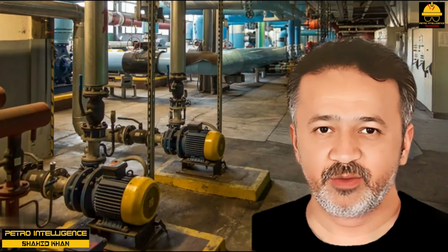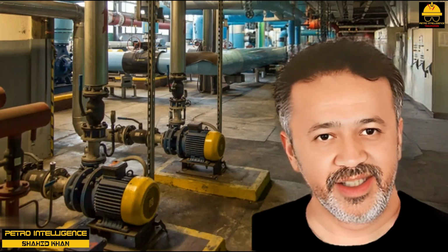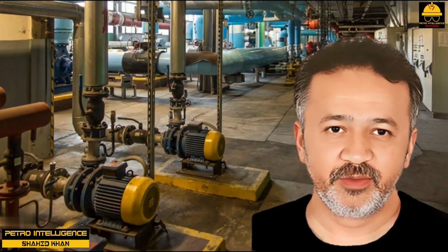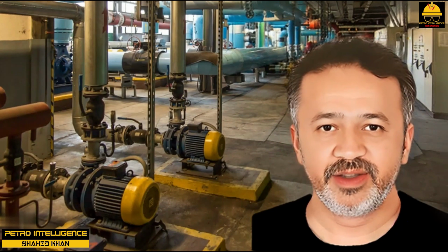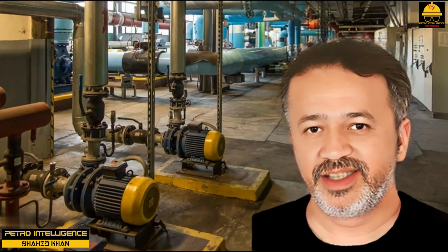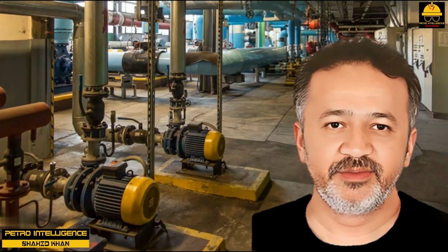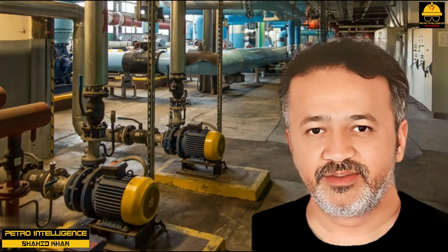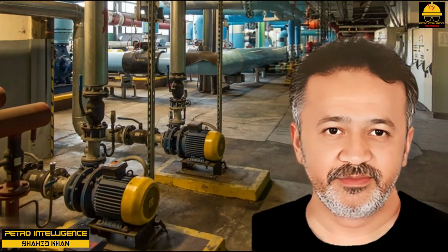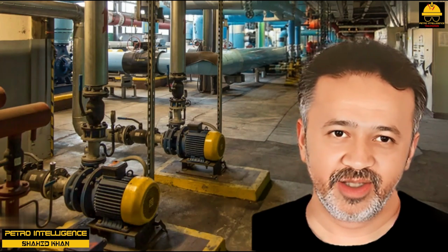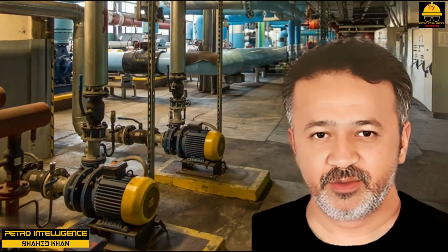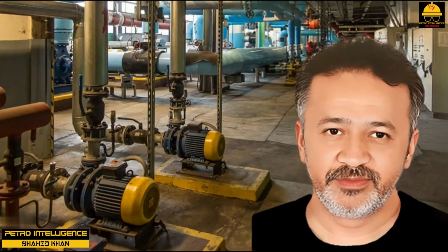Reducing the turbine exhaust pressure will not significantly increase the steam flow to the turbine. However, reducing the turbine exhaust steam pressure will increase the amount of work that may be extracted from each pound of steam. For example, 150 psig, 400 degrees Fahrenheit steam is being used to drive a turbine. The exhaust steam is flowing into a 15 psig steam header. By venting the steam to the atmosphere, the amount of work that can be extracted from each pound of steam will increase by roughly 30%. Check the Mollier diagram.